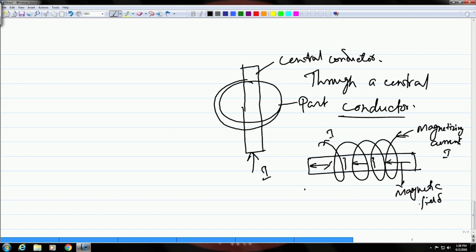Okay. So, 45-degree cracks and transverse cracks which are perpendicular to this axis have good visibility in this case, because the magnetic field is longitudinal.